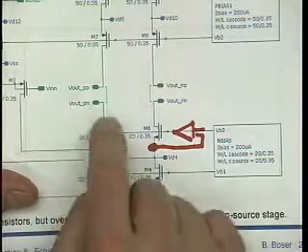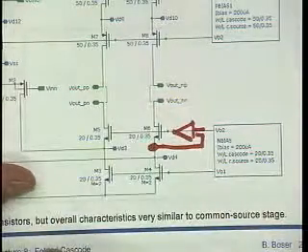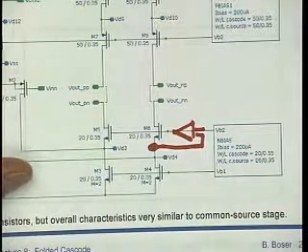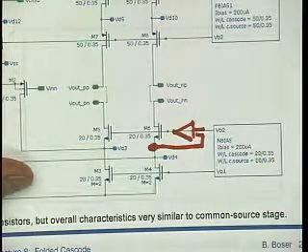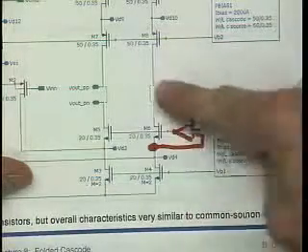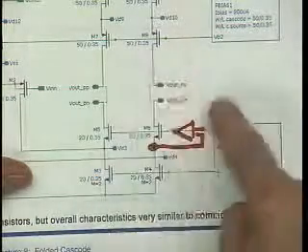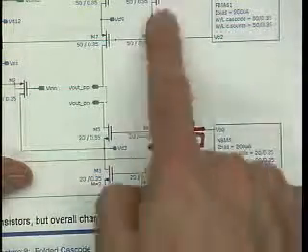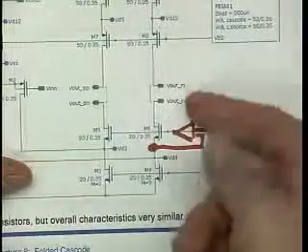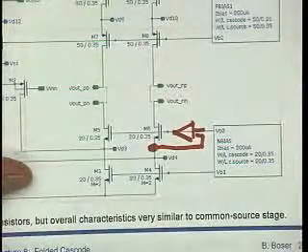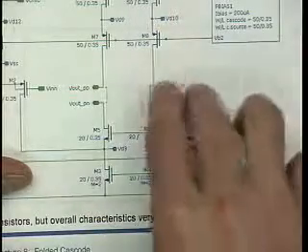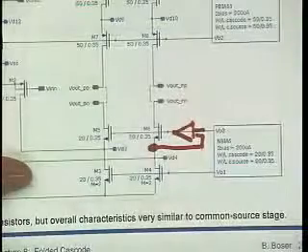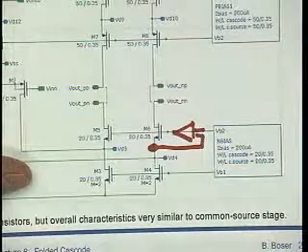Most of the time, I just tie those together, right? But when I want to know what I need to do in order to increase the gain of my circuit, I go and force a current into the NMOS, and I force a current into the PMOS, and do a small signal analysis to measure the output impedance as a function, presumably, of the DC output voltage, the bias.